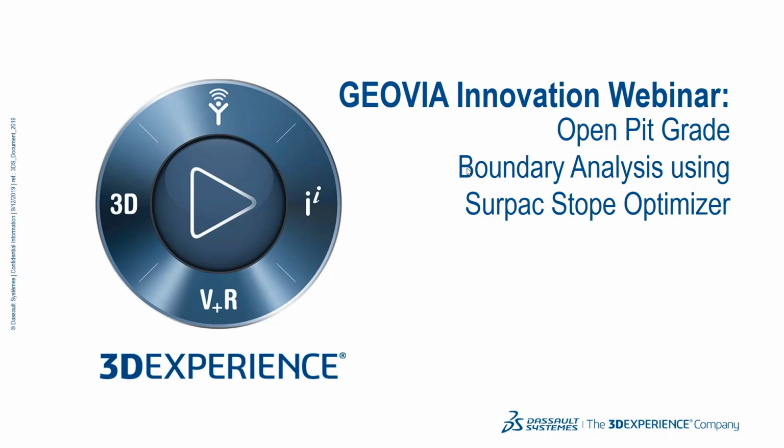Let that run. Typically run times for the Stope Optimizer depend on the size of the block model that they're dealing with, and the number of stope frameworks that you're wanting to evaluate over your block model area. You may have more than one stope geometry that you need to use over your block model, and you may need to set up subdomains to do that.